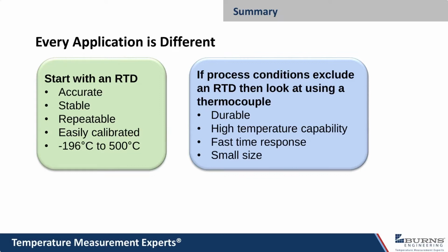And if we're going over 500 C, a thermocouple is usually the best option. If we need a super fast response time, that's going to go to the thermocouple also, just because of the really small size. When we look at how they're made, you'll see that the technology can respond faster to temperature changes.